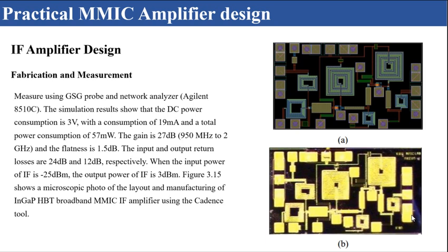The gain is 27 decibel and the flatness is 1.5 decibel. The input and output return losses are 24 decibel and 12 decibel respectively.